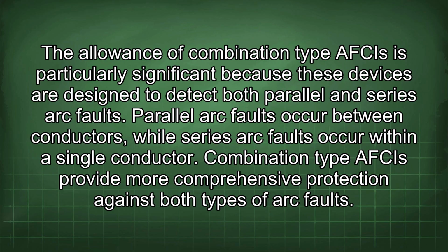The allowance of combination type AFCIs is particularly significant because these devices are designed to detect both parallel and series arc faults. Parallel arc faults occur between conductors, while series arc faults occur within a single conductor. Combination type AFCIs provide more comprehensive protection against both types of arc faults.